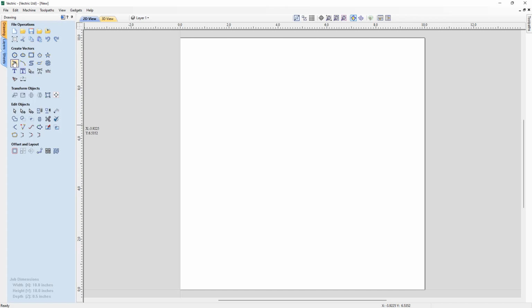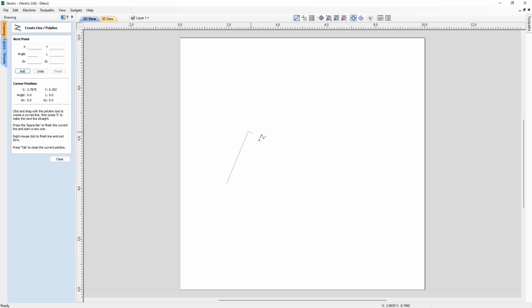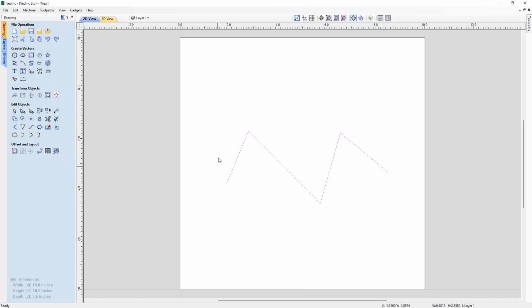Okay, and then we're just going to go back into the Polyline tool where I just want to demonstrate how you could make a curve from the polyline. So here you can see we've got a series of spans that I've just created, and if you go to node edit mode by pressing N on the keyboard, you can see that those nodes are now visible to us. So each point is a node, okay?